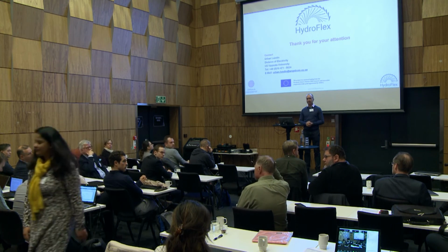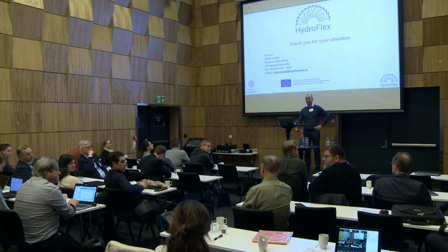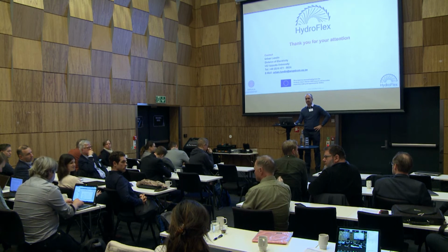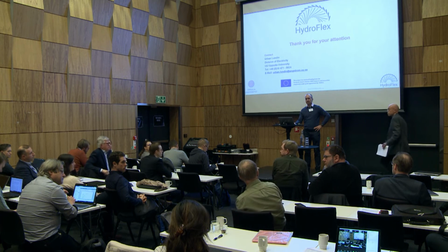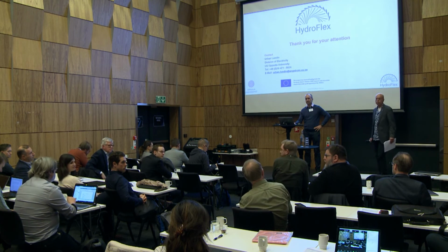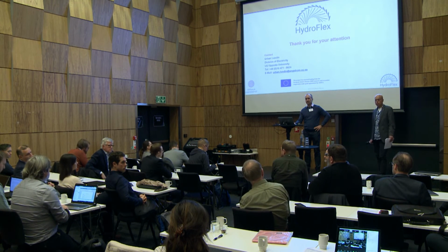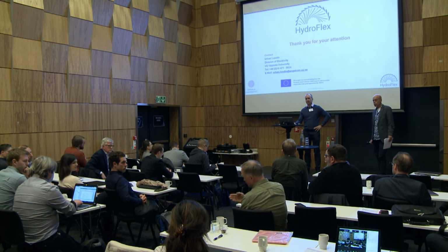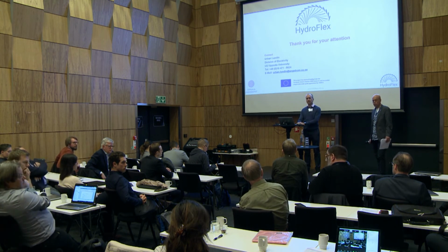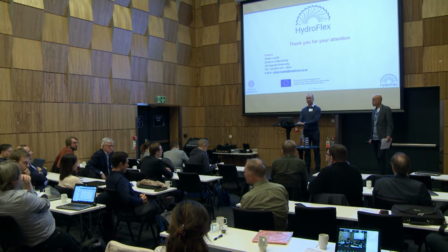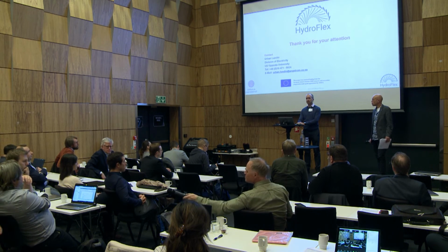Just a comment on Grimsel. It's a retrofit installation, and we have a power transformer between the converter and the original generator, so we are avoiding these insulation problems. But I think that Indar is installing 2 units in Spain now, 50 megawatt each, and I think those are using this NPC technology directly connected to the generator. So development is going in that direction.